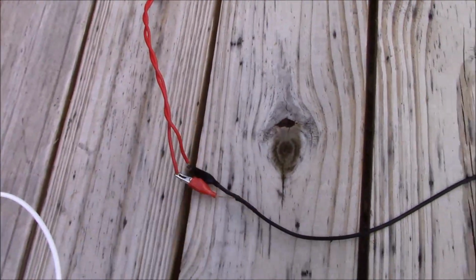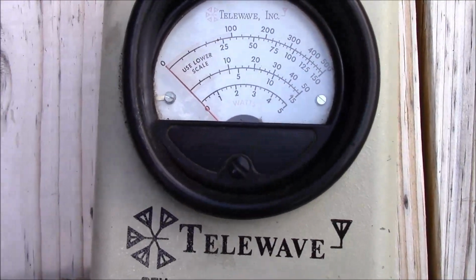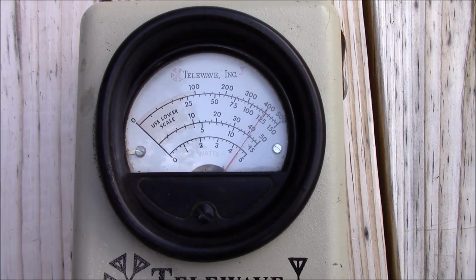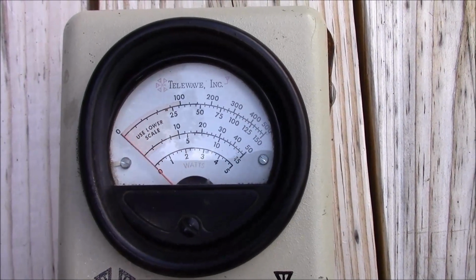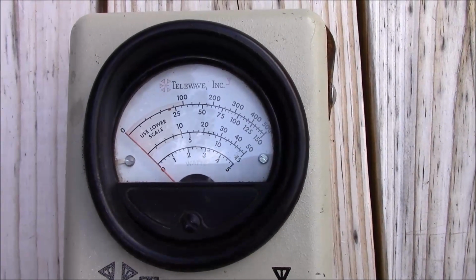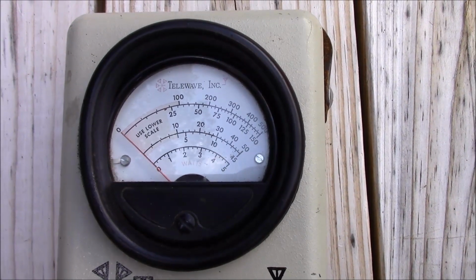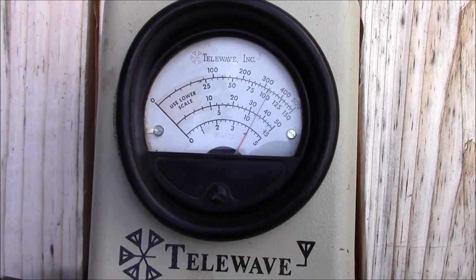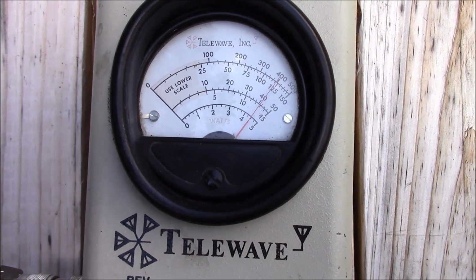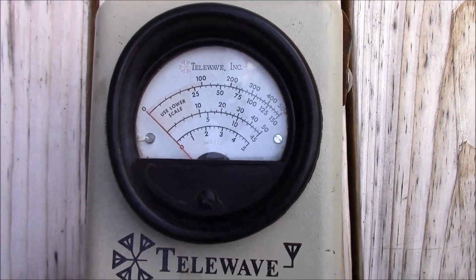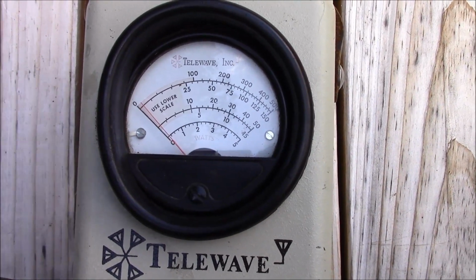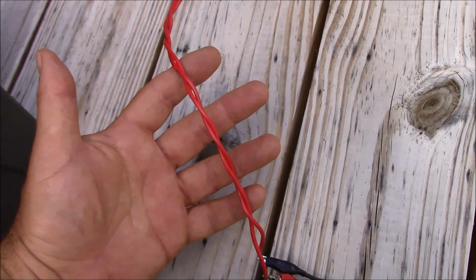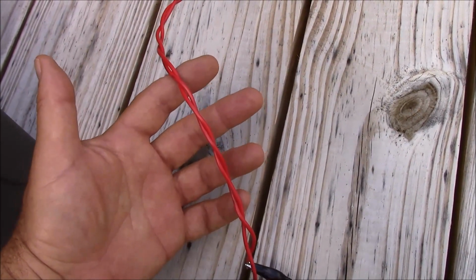See how our 16 gauge twisted pair handles power. I'm going to start with an HT, 4.5 watts forward. Barely moving the needle in reflected power. Well, let's see how our homemade twisted pair handles mobile radio power. 40 watts forward. Barely moving the needle on reflected. So it's obvious that the larger size conductor handles RF better than the Cat 5 twisted pair.